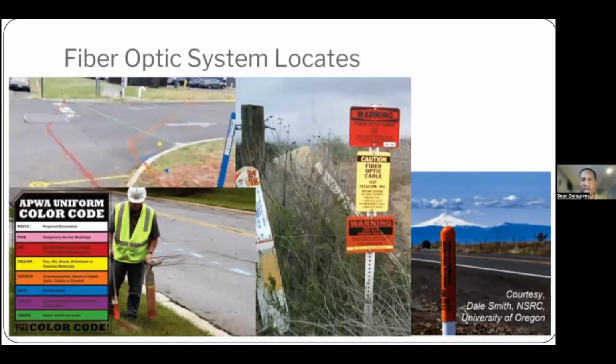Another challenge when it comes to underground deployment is you have to have a really good, precise sense of where other underground utilities are, gas, water lines, etc. And so finding where those are, and then even when you deploy your fiber, carefully marking it, because you don't want somebody to come along with a backhoe and accidentally cut your fiber line, which actually happens. Now, of course, when you deploy fiber underground, it's less impacted by environmental factors, storms, etc. So sometimes when you have storms that are knocking out utility poles and power goes out, fiber that's underground often is unaffected by any of that. But of course, when you're digging and deploying fiber underground, as wonderful as that fiber connection may be, you don't want to hit a gas main.